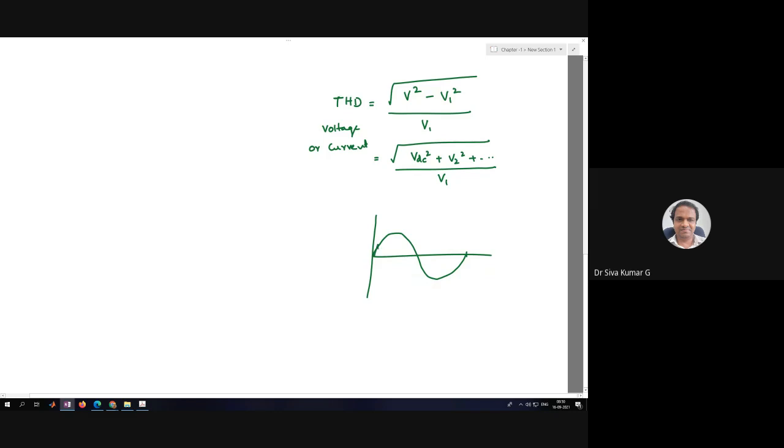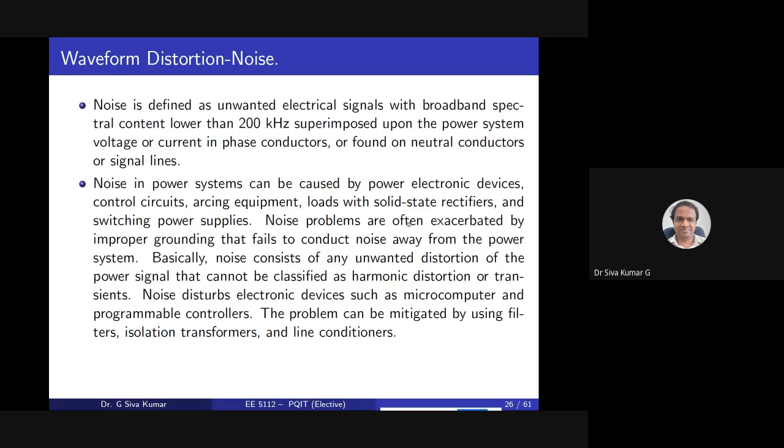Suppose there is noise over here, maybe the zero crossing is going to occur at this particular point also. Again it starts rising over here, this kind of a signal. The occurrence of the zero crossing may be twice. One point is this, the other point is this. If noise is there, it goes something like this, and this particular point has occurred at 1, 2 and 3. It has reset almost 3 times. Basically, that kind of problem will be there.